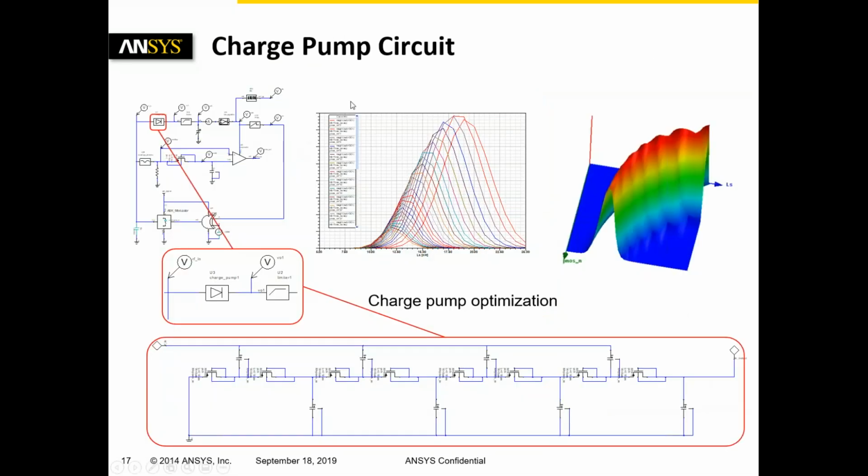So then we will look at the charge pump circuit. The top schematic is for the charge pump, which is the rectifier circuit used in the design. It used diode connected MOSFETs as rectifiers. It is the most unique and probably most important part of the RFID tag front end because its efficiency is directly linked to the operational range of the tag.